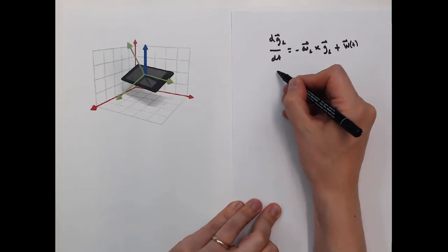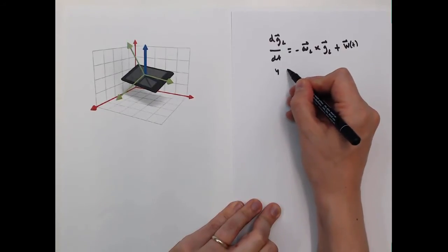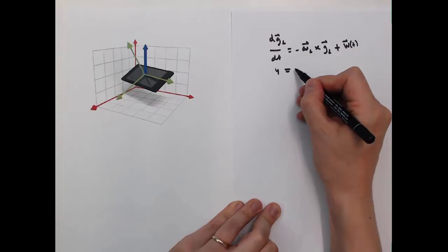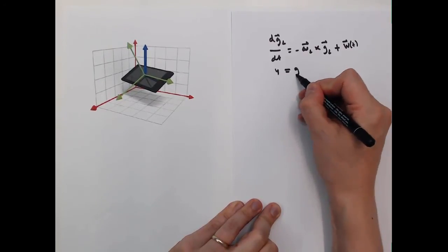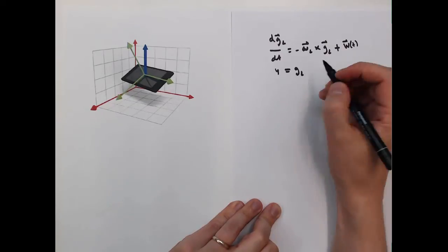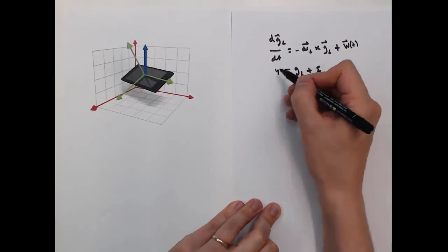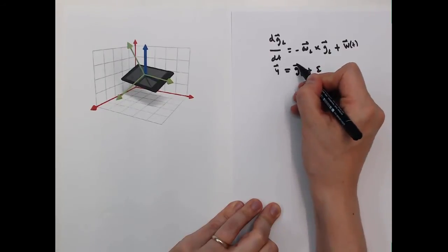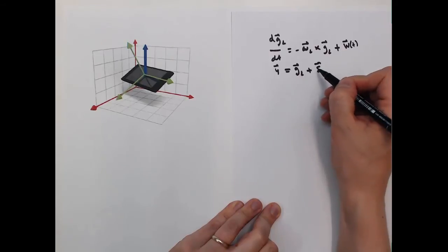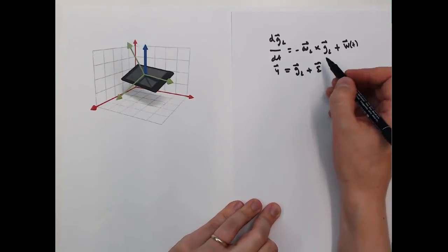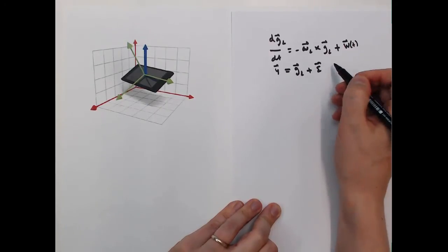And you can actually use this for tracking the orientation by postulating the measurement model. So you think that you actually measure using an accelerometer the local gravitation plus a noise process. So it's a 3D measurement and 3D noise. And then you absorb, or actually model, the linear accelerations in addition to the gravitation into this noise component.